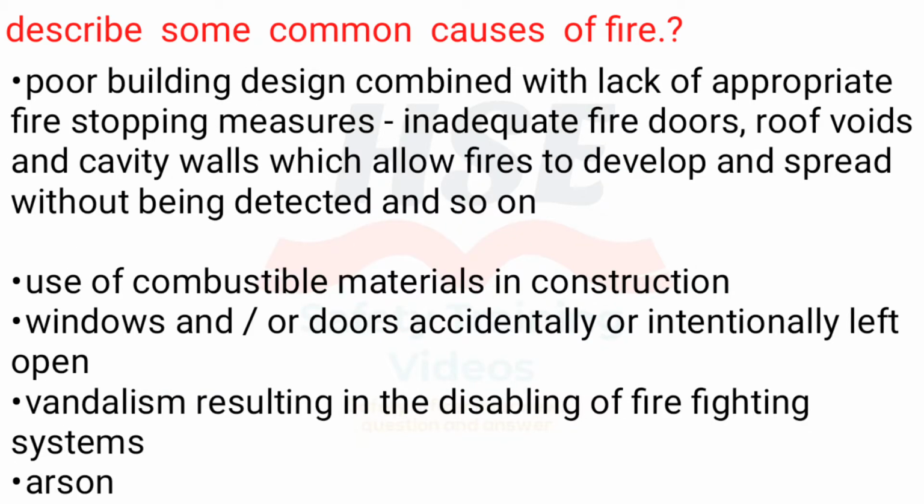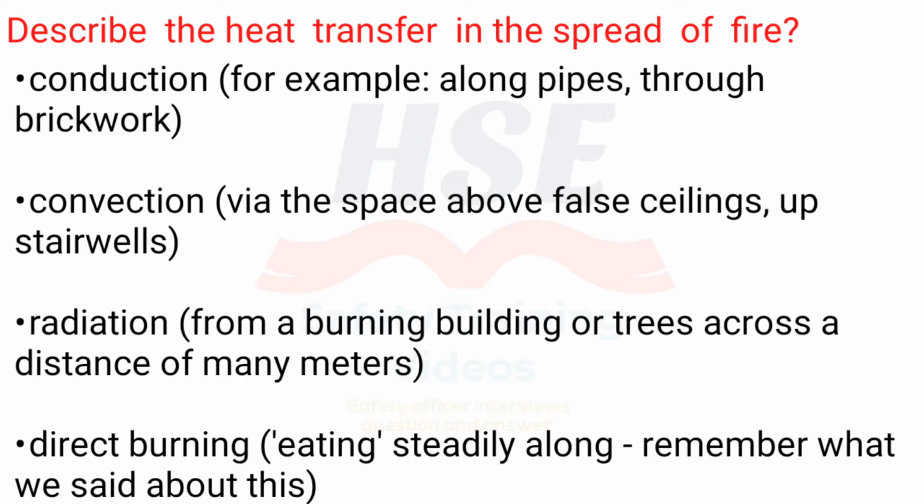Poor building design combined with lack of appropriate fire-stopping measures, inadequate fire doors, roof voids and cavity walls, which allow fires to develop and spread without being detected, and so on. Use of combustible materials in construction. Windows or doors accidentally or intentionally left open. Vandalism resulting in the disabling of firefighting systems. Arson.